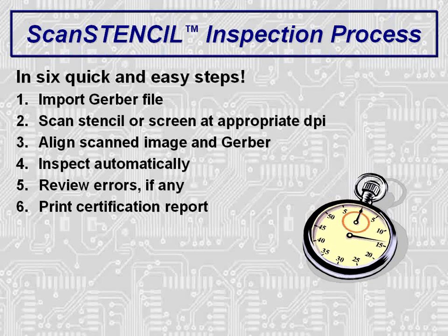Stencil inspection can be performed in 6 quick and easy steps. First, import the Gerber data or CAD data. Next, scan the part to be inspected. Then automatically align the scanned image to the Gerber data. Perform an automatic inspection with the required tolerance.